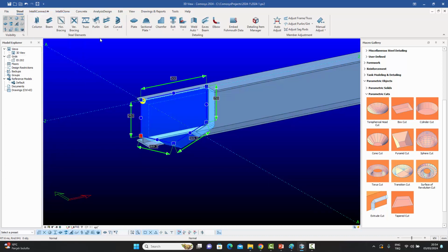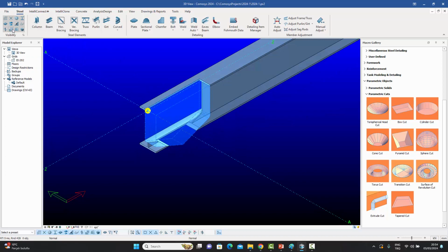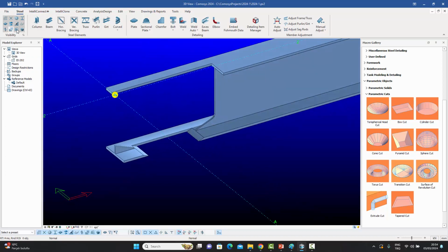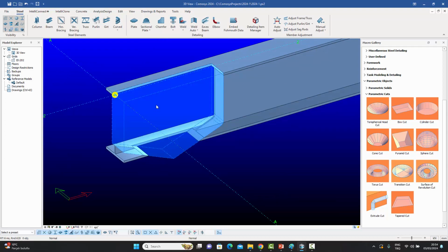I can do that. And if I remove the cuts from the screen, you can see how I have cut my object. So this is extremely useful because after creating the cut through the tapered cut command, you still have the definition points on the screen and you have the handles on the screen. You can give chamfers to the corners. You can insert new points in the cut.